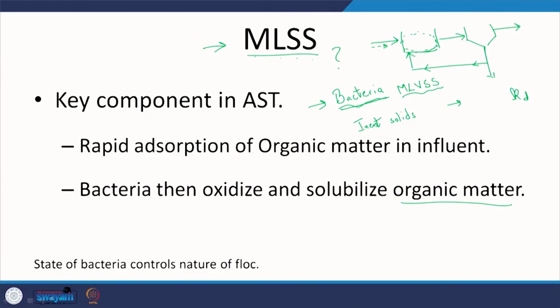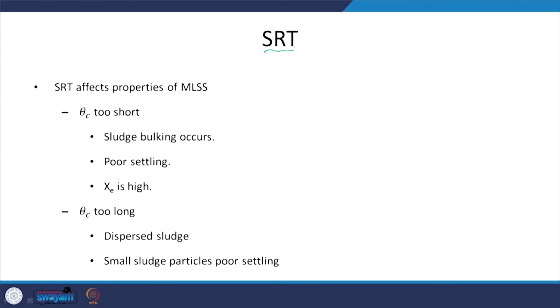So let's move on. Solid retention time, some aspects that we need to be aware of. First, this is not HRT. HRT is about hydraulic or water. This is about solids, and when we say solids, we are referring to the microbes. So SRT affects the properties of MLSS, obviously. Why is that? I have this tank and this is the recycle, right? So the recycle and the concentration will affect the time that my microbes are spending in my system.